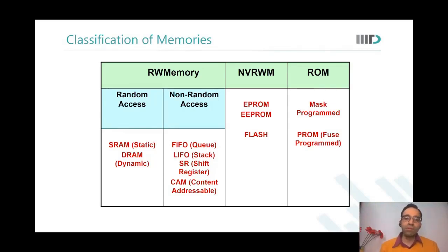Okay, so this is about the access pattern. They are random access memories. What does random access mean? So we can write or read from any particular location at any particular time. Yes, I will give an address to the memory, and I can read or write any location. So where are SRAMs? The DRAMs we already discussed. SRAMs would be typically used as caches, for example, L1 cache, L2 cache, and so on, where you have an instruction which may carry an address and you want to write at that address.